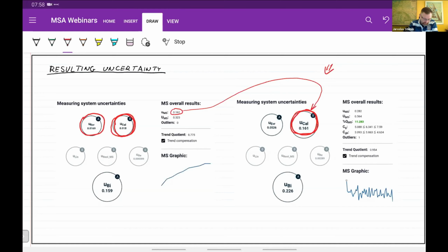And this repeatability experiment contributes the repeatability and the bias. So having the calibration value and having the value which is actually measured on that standard gives the bias, gives the relation to the precise value which we want to have. Of course, it's burdened with the repeatability. That's the reason why it's there. We get the overall measurement system uncertainty. We plug it into the second one, into the actual production unit, and we land with what we want to have.